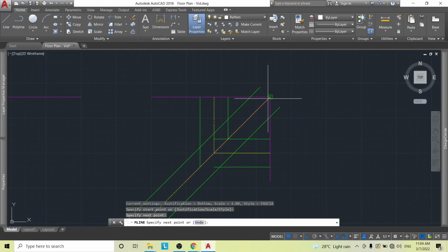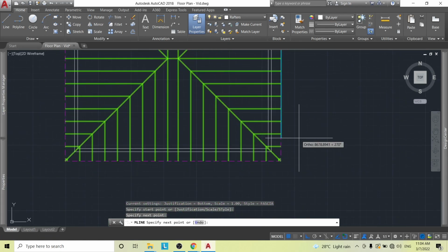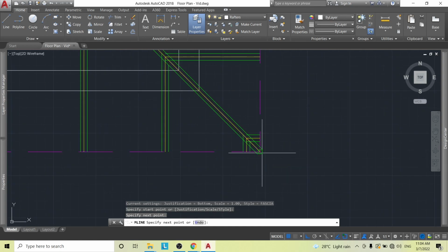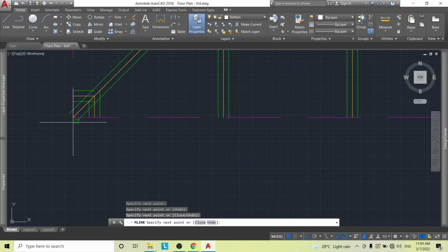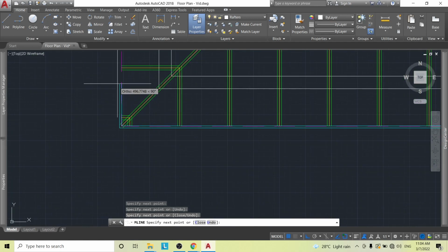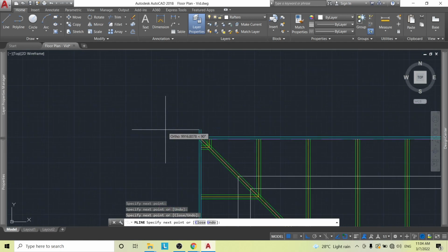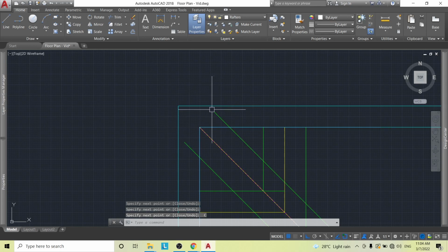When you bend the corner, you will see the line make a little elbow by itself. Click the other corner, like that, and then come around the bottom. You would notice that the rafters are crossing the lines. That's okay. We will fix that later, just like how I said we'll fix the other one. So here's what you do. You carry it up to this point, click there. Now you have this little piece left. How do you fix it? Down here you would see it says close. You can click that and then it's going to close off the multi-line for you.